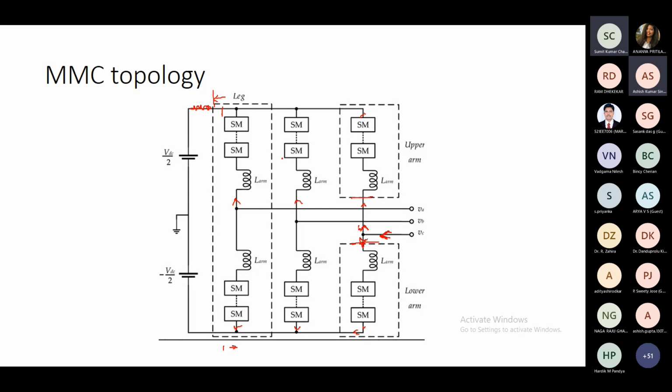Those will have ripple, and those ripples are phase shifted. Those will cause a circulating current, and that will increase the final magnitude of the current handled by all the components: inductor, capacitor, devices. So the peak current for all the components will be increased. For this, circulating current control is there. But again, it is no rocket science. It again comes from the very basics.